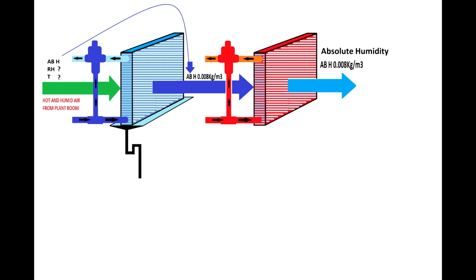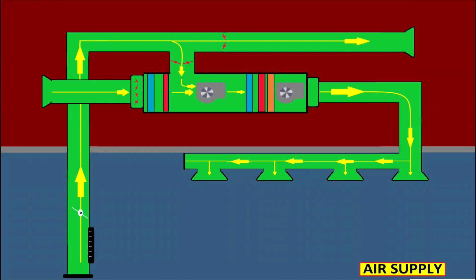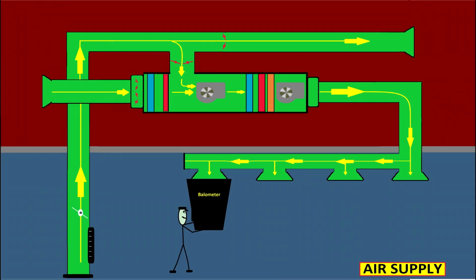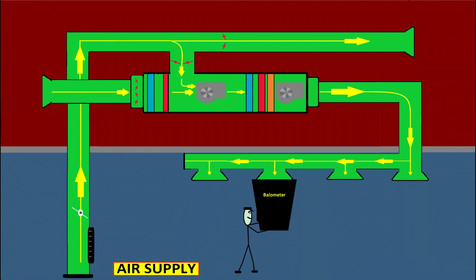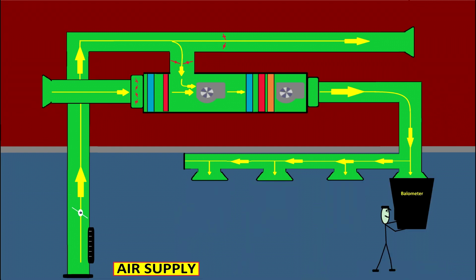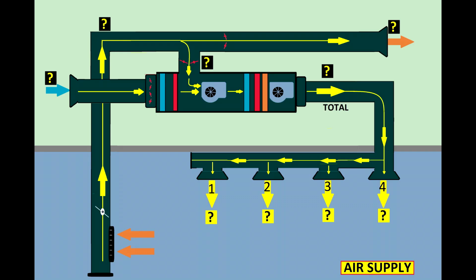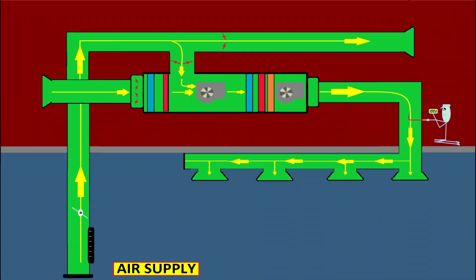So it is very important to have an appropriate calibration, so we control the airflow and do not exceed the maximum quantity of air that can pass through a heat exchanger as per its specification. If you remember, I talked before about taking measurements from multiple locations. So here, if we use a balometer, we take the measurements from inside the rooms, and then the sum of all these outlets should be equal to the measurement I'm doing now on the supply air duct. Or if I have some losses, then I have to subtract that value.